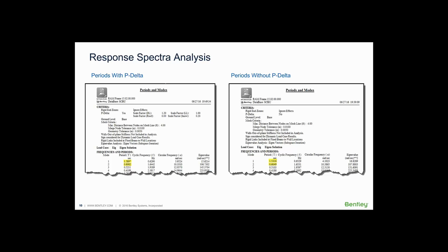That would give you a closer answer, but you would still miss the effects that P delta has on the seismic forces. Back to the overturning on a column, you've got the vertical load from the seismic load hitting this column, and that approach would miss the additional moments induced by those P delta effects on that vertical load acting on that column.